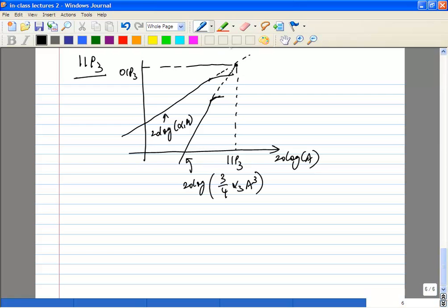Right? So those are the two curves we are plotting. Alpha 1 a was the gain of the fundamental. Remember the definition of IIP3 requires you to use equal amplitudes and two tones. Quite often you'll find people calling it a two-tone test. So they'll ask you, have you performed the two-tone test on the LNA, right? Because you're giving two equal tones.